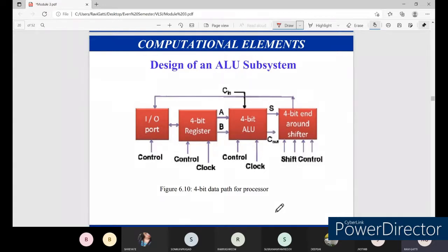The fundamental goal of this arithmetic logic unit is to do all the 4-bit addition operations and all the logical operations which are associated with the 4-bit adder we are considering. Basically, the 4-bit adder performs the addition of the 4-bit operands and produces the result. When it produces the result, we will have two outputs. What are those outputs? We will get one sum and one carry.